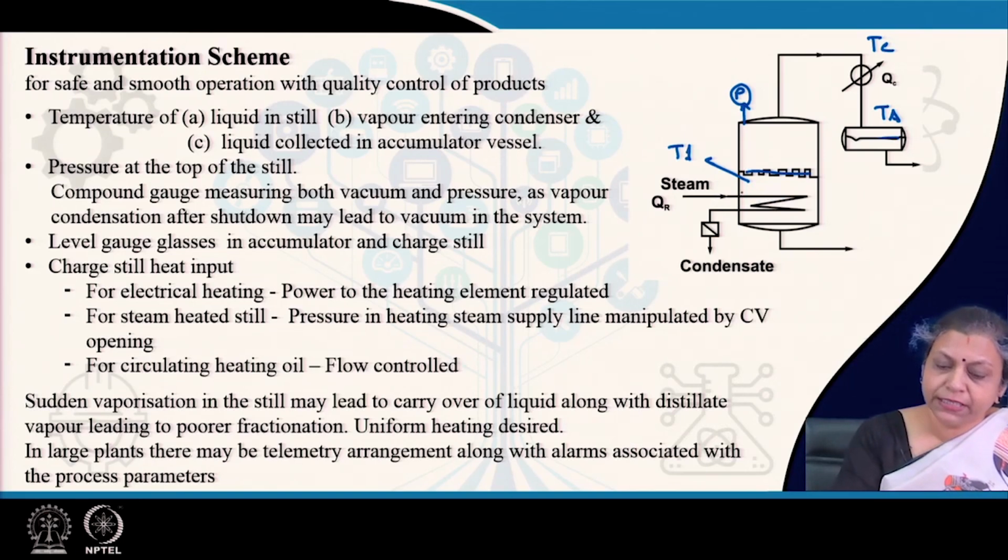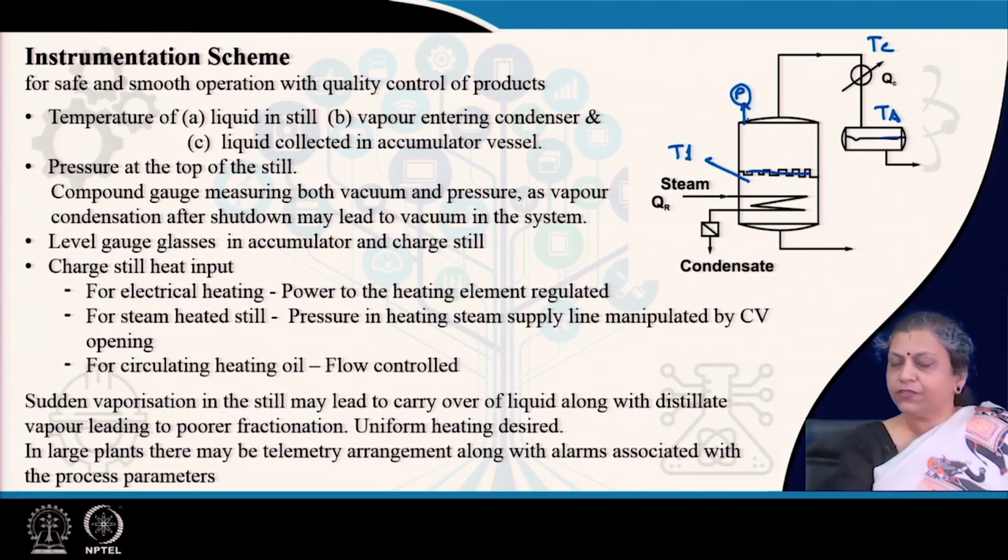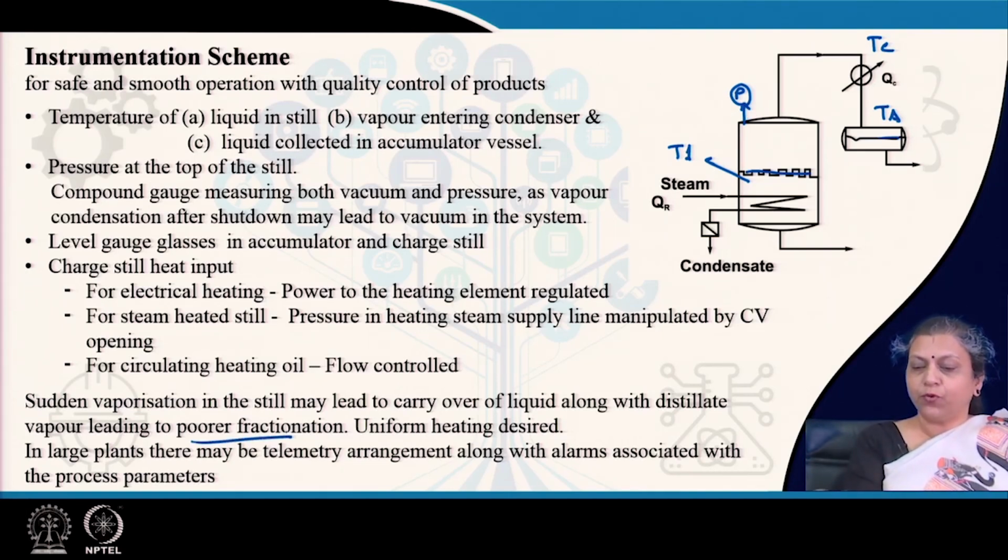Therefore, the heating rate should be controlled, and it should be as uniform as possible, because if suddenly a huge amount of heat is given and there is a lot of vaporization, there is every chance that the vapor will entrain some amount of liquid and take it along with it, and that will reduce the efficiency of the distillation. It will result in poor fractionation. So, uniform heating is very much necessary, and the heating rate is necessary because that tells you the duration of the startup period and also the rate of distillation.